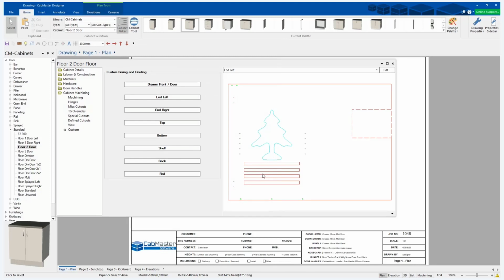So depending on what shape you want to do, if it's a common thing you want to do, it could be for a daisy chain, or it could be some cutout for a water pipe or electrical plug, absolutely. You can write a custom table that then is parametric. You can also do custom tables that can get edited inside the drawing properties.